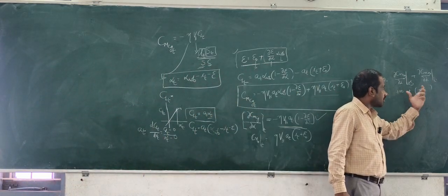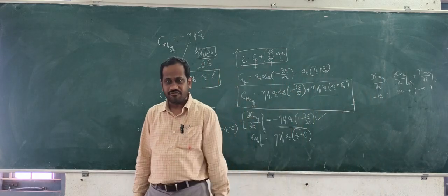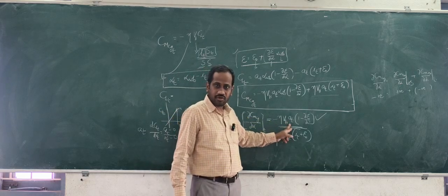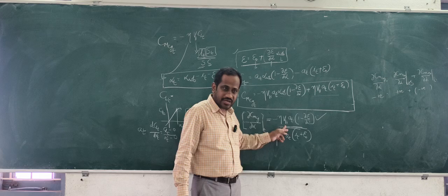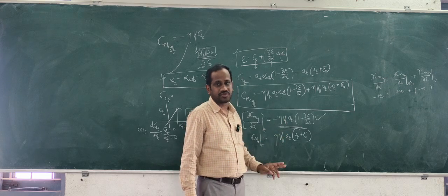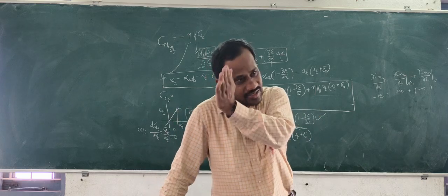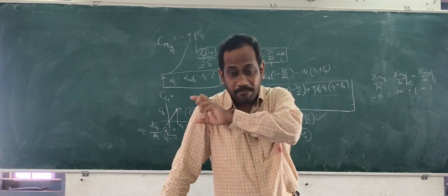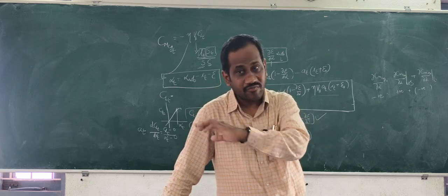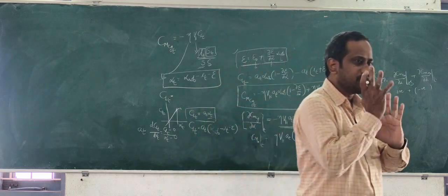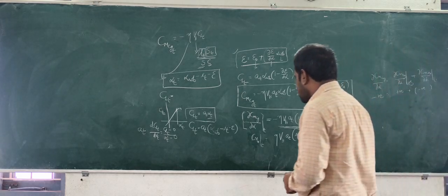So, what are all the choices you have? The choices are only selection of aerofoil and its slope of the lift curve and horizontal tail volume ratio. So that's all. Horizontal tail volume ratio means location of the tail is also one parameter and planform area of the tail is also another parameter in the numerator. In the denominator, wing parameters are there. So that ratio should be the crucial parameter. Just look at once. Did you get the point?